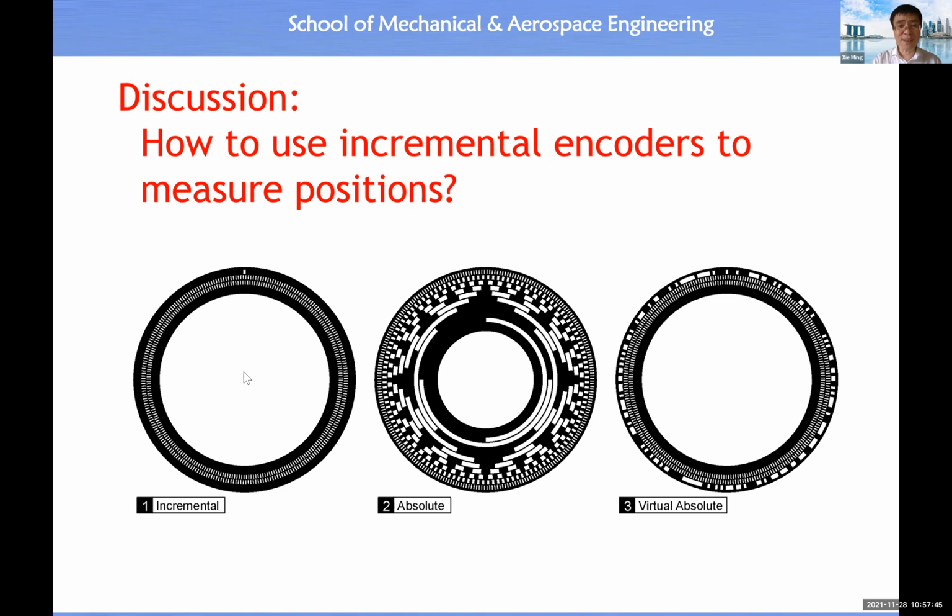And from this design for the velocity sensor, you see it's quite simple. We only have 3 tracks. Okay, regardless of what the dimension of the disk is, just 3. Then could we combine the advantages of both? Then the answer is yes. Okay, so we still maintain the capability of this velocity sensor for the measurement of displacement, because we only need to know what the zero position is.